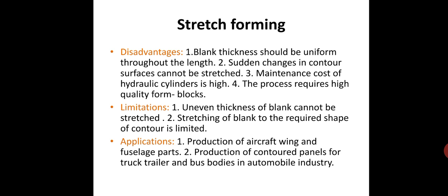The form blocks are made up of the exact shape and size of the required object. And what are the limitations? Uneven thickness of the blank cannot be stretched. Stretching of the blank to the required shape of the contour is limited.